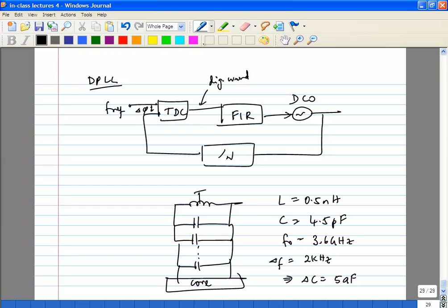Metal to metal capacitance, exactly. Turning on that switch parasitic, of course. So your switches need to be extremely small, so you may not be able to do it in the latest process, but in older processes like 65 nanometer or 45 nanometer, you'll probably be able to do it. People have implemented these, and they work pretty well.